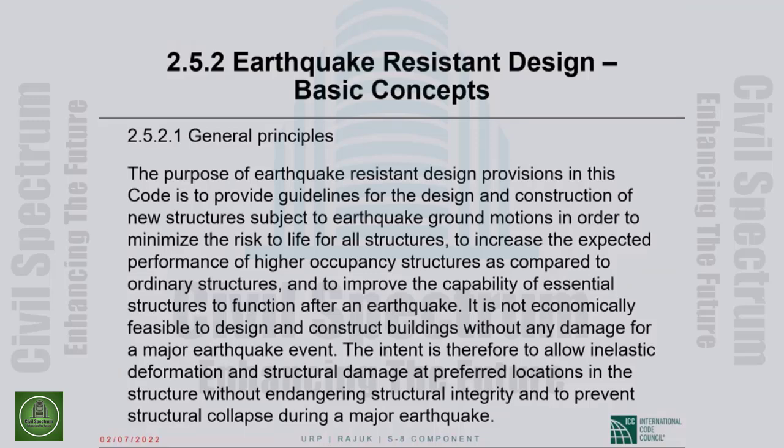This is important. It is not economically feasible to design and construct buildings without any damage for a major earthquake event. The intent is therefore to allow inelastic deformation and structural damage at preferred locations. Yes, we'd like to choose the locations of damage, at preferred locations in the structure without endangering structural integrity.